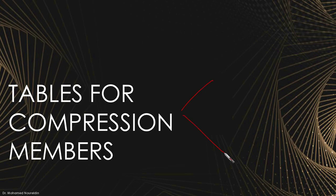Broadly, one is table 4-22, which we go through by KL over R. The other is from 4-1, if we're talking about the wide flange, to let's assume 4-20. These we call column load tables, and we use KL here.